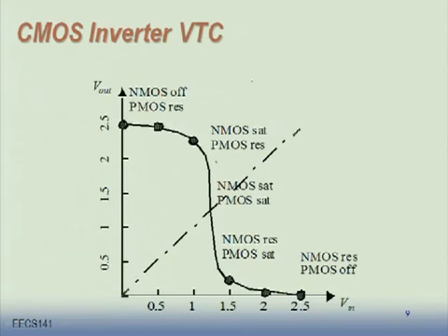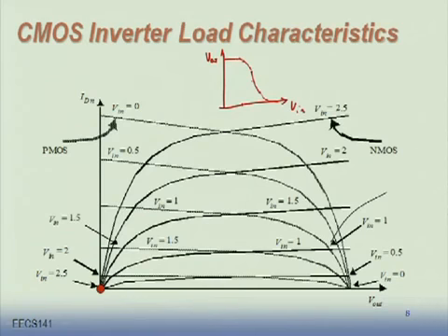Now what is going to happen here is when NMOS VGS becomes large enough, this voltage starts dropping down. When NMOS starts conducting over here, around these points, in which region of operation is NMOS? It's saturation, or maybe velocity saturation. Well, here would be saturation according to our model. Here it gets into velocity saturation. You have to check that. And then as it goes through, it's definitely velocity saturated, and eventually will become linear again.